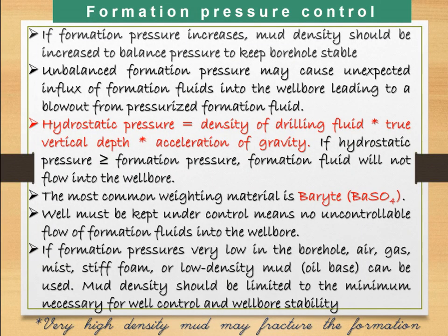Further, now these are about cutting material removal. Now another important thing is formation pressure control. Because as I have told, if formation pressure increases, mud density should be increased accordingly to balance the pressure to keep the borehole stable. Unbalanced formation pressure may cause unexpected influx of formation fluids into the wellbore, which can lead to a blowout from pressurized formation fluid.